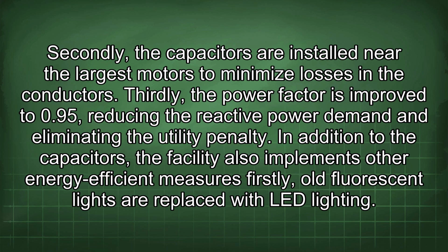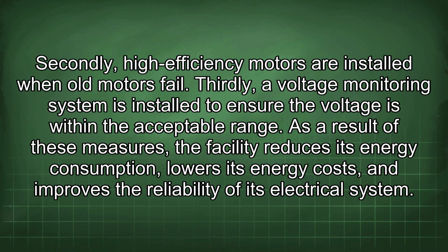In addition to the capacitors, the facility also implements other energy-efficient measures. Firstly, old fluorescent lights are replaced with LED lighting. Secondly, high-efficiency motors are installed when old motors fail. Thirdly, a voltage monitoring system is installed to ensure the voltage is within the acceptable range. As a result of these measures, the facility reduces its energy consumption, lowers its energy costs, and improves the reliability